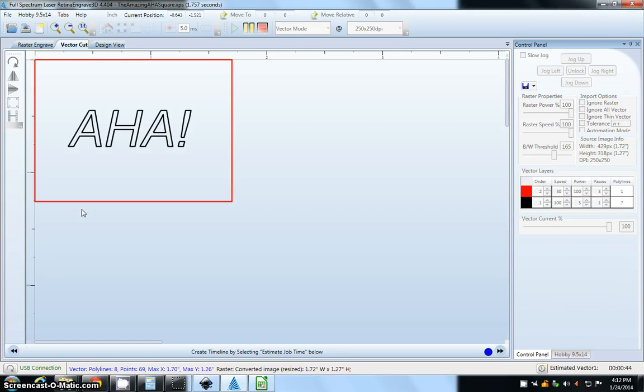But when you are laser cutting, you want to stay with the laser cutter. If horrible flames burst and bad things happen, there is a fire extinguisher usually located just next to or behind the laser cutter, so know where that is. Two, there's a big red E-stop button. If something horrible does happen, just smash that E-stop, and that'll stop the laser cutter. It won't work again until you reset the E-stop button.